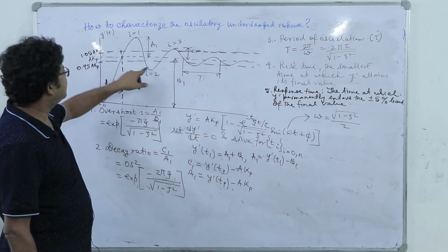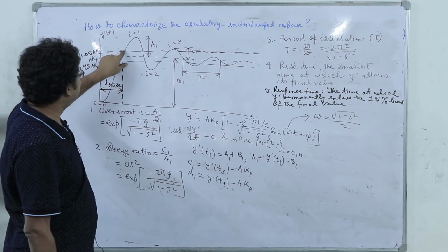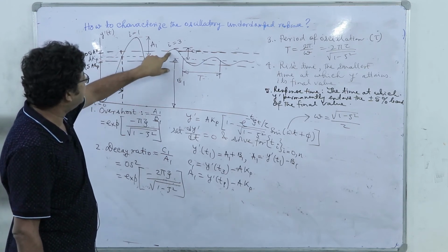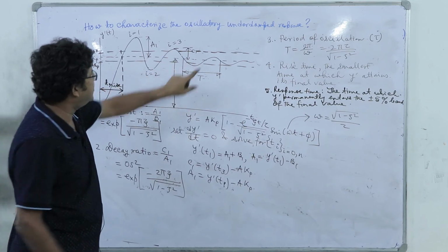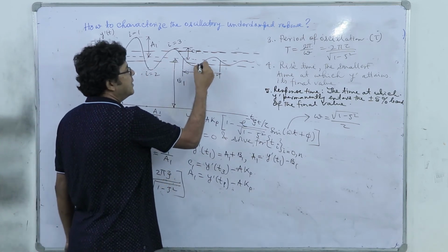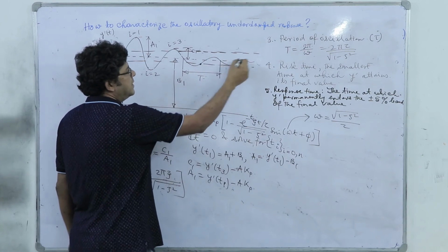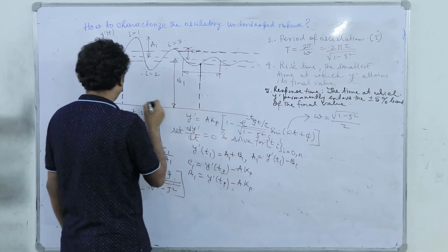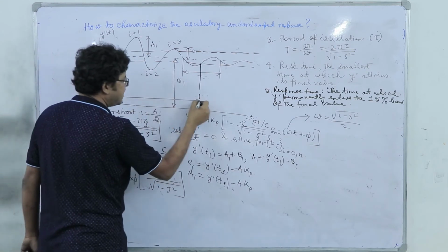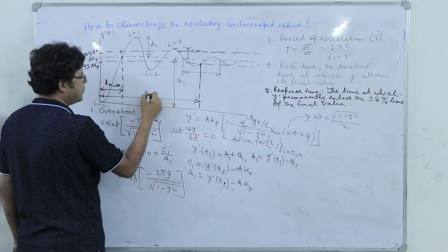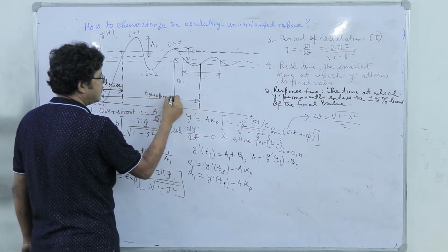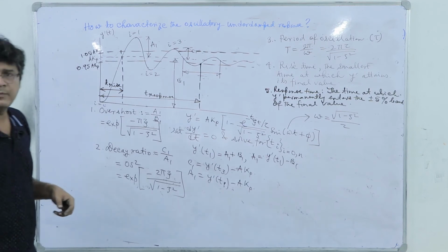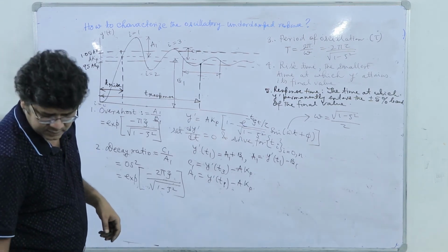So, you see that here it enters, but again it moves out. Here it enters, again it moves out. Here it enters, again it moves out. Here also the same. But after this point, once it enters this band, it never moves out of that band. So, this is the response time. Okay, these are all the response time of this second order system.